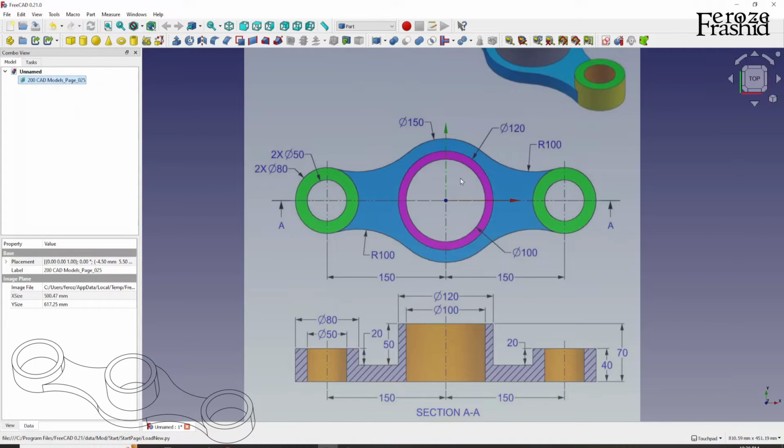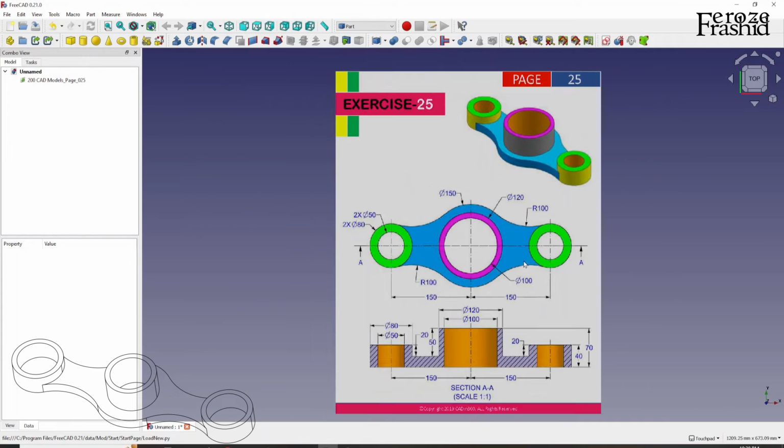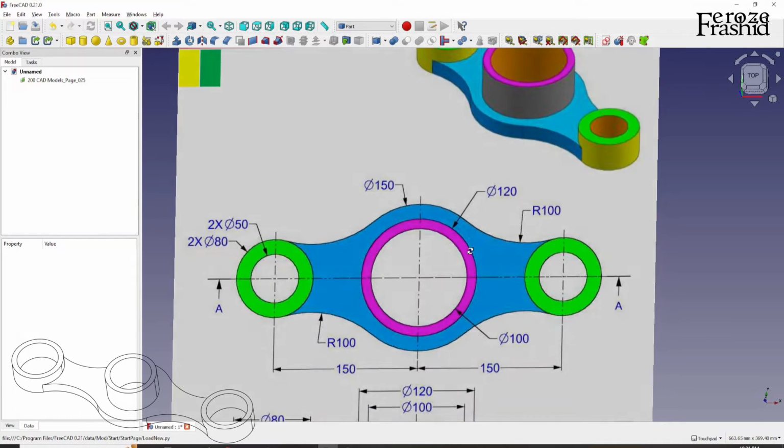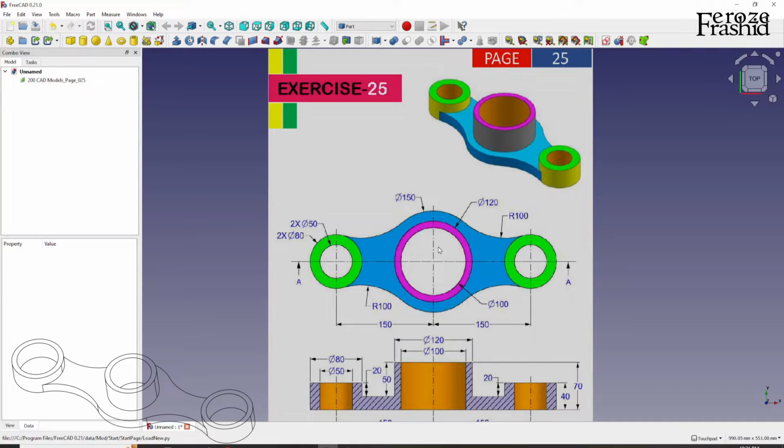Let's take a closer look at the object. It is symmetric with this axis, the YZ plane, and also symmetric on the XZ plane. So we can create only 1/4 of it, like we did in one of the previous videos. But because I'll be using primitives to create these three cylinders in the middle, I will have to create only this part, this connector in the mirroring part.